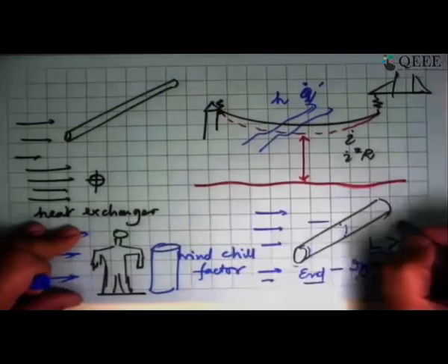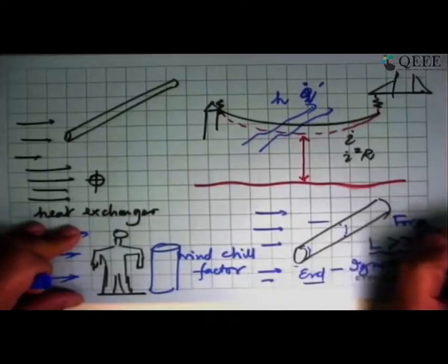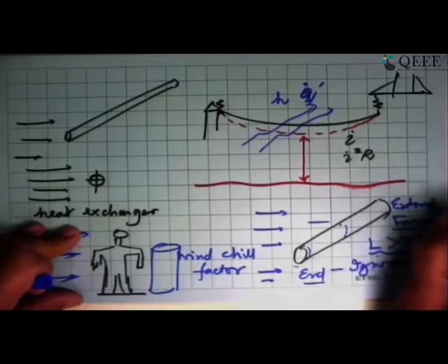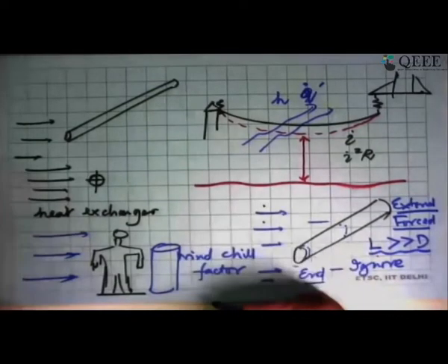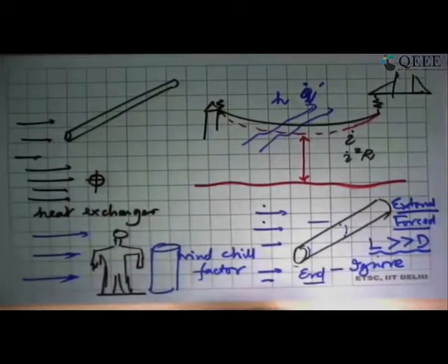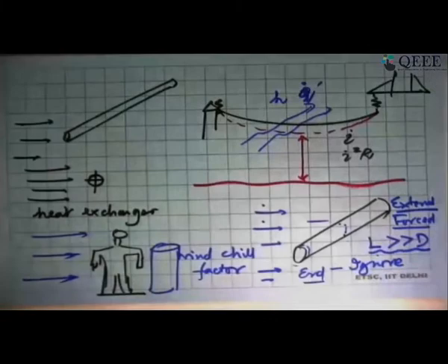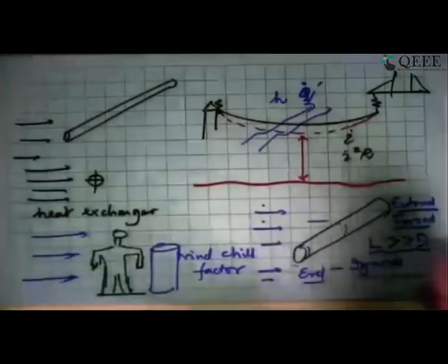Okay, so this is one condition we are doing. We are saying that this is a forced convection problem. It is an external flow, and that oncoming flow is laminar. In the real case, it will definitely be turbulent flow, but we'll look at it differently. We'll start with laminar and see what happens. Well, the way to understand what happens on the cylinder is to understand what happens to the flow over the cylinder, and we will understand that by looking at some pictures.